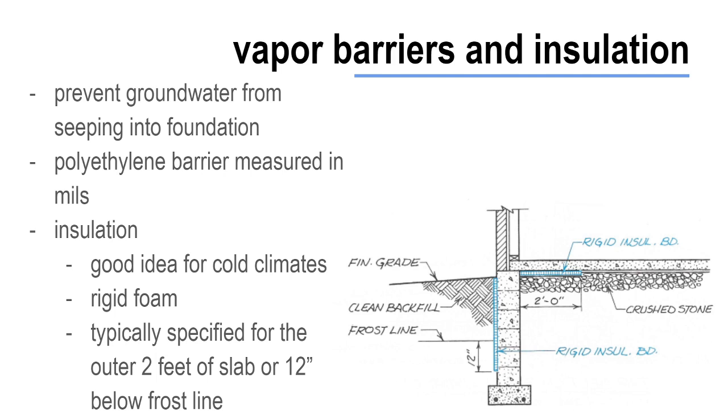And you shouldn't do it until the superstructure, the wood structure above the foundation, has been framed as well. The weight and the rigidity of the floor on the foundation wall help the wall to resist the pressure of the backfill. If you do have to backfill before framing, then the foundation wall should be braced.